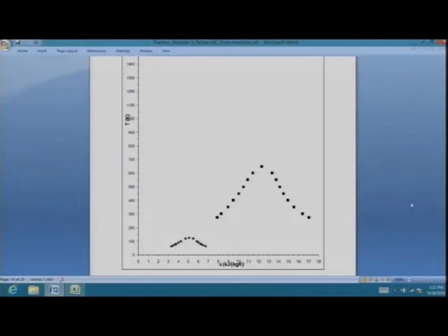And with respect to that, I replotted SF and SG on the TS diagram. So now we are looking at a consistent set of specific entropy for two very different substances, whereas according to tables, nitrogen is referenced to some temperature, water is referenced to 0.01 degrees Celsius. We cannot directly plot the two on the same diagram, but this is consistent now.